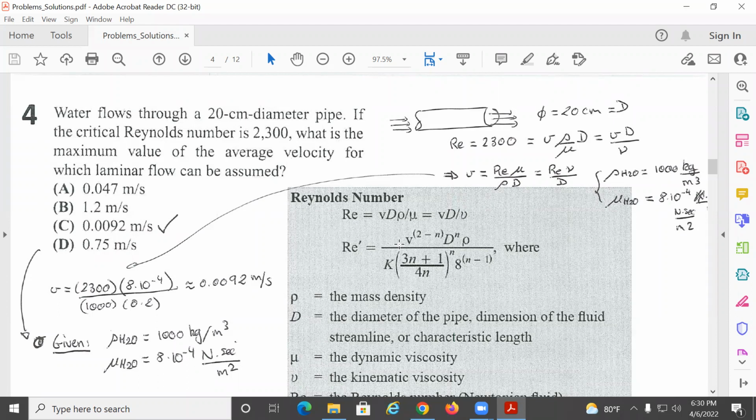So this is for water, and I'm not that familiar with water, but for air, I think a Reynolds number above 10,000 basically means turbulent, and under 10,000 is laminar flow. But for water, the densities are larger. So the larger the diameter of the tube, the more water, so it would probably be laminar. If it is smaller, it will increase the velocity, and probably the flow will then be turbulent. But basically, they tell you it is laminar with this density.